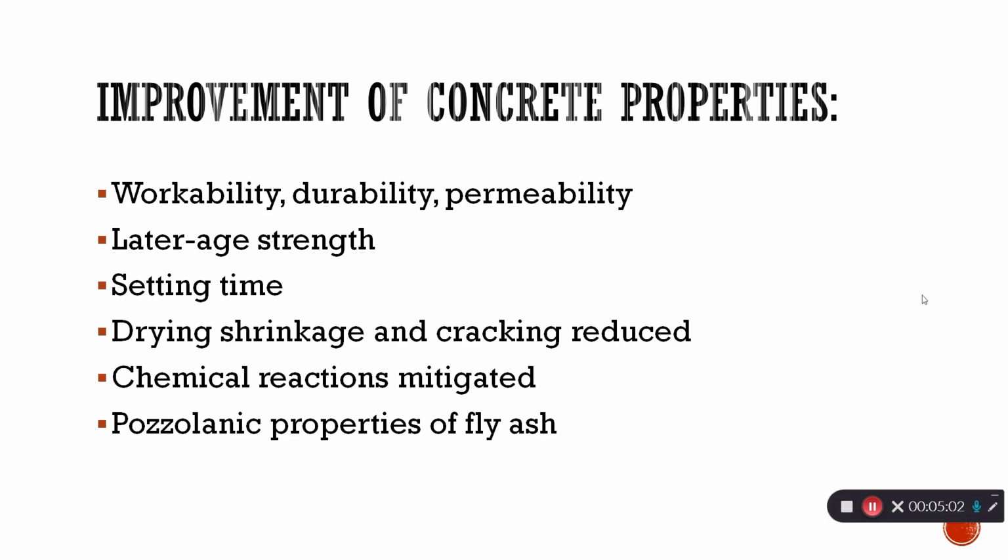The improvement of concrete properties. High-volume fly ash can change and improve concrete's properties when used in a concrete mixture. Examples of changing and improving the concrete's properties are the workability of the fresh concrete that can be enhanced, the later age strength of the concrete can exhibit increased strength compared to conventional concrete. The durability can be improved. The permeability can be reduced, and this improves the resistance to water penetration in the concrete.